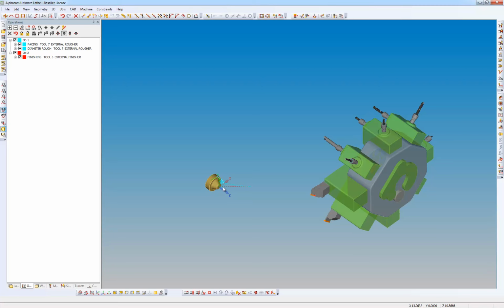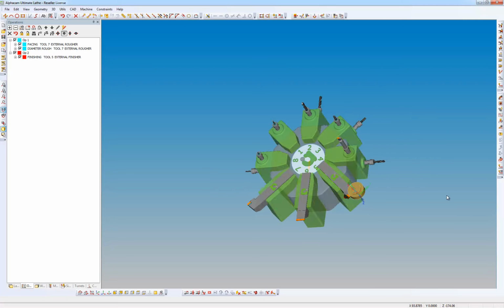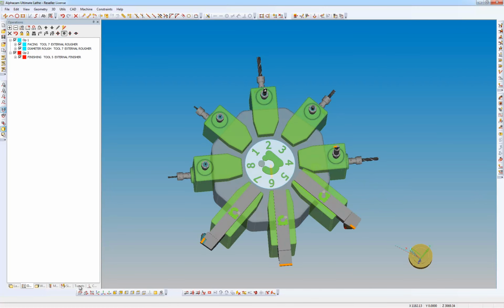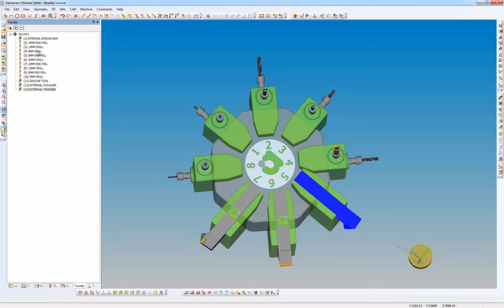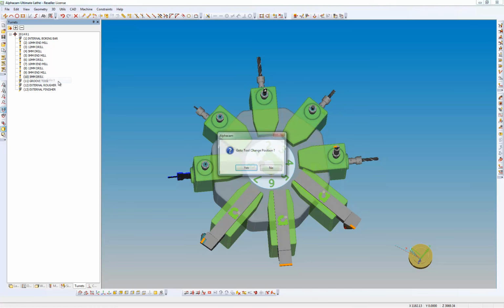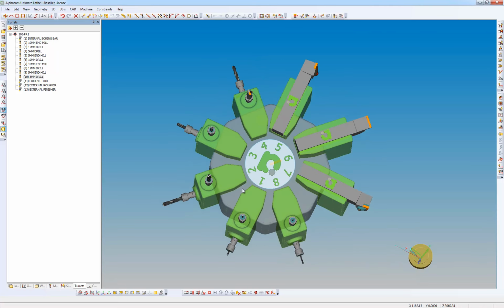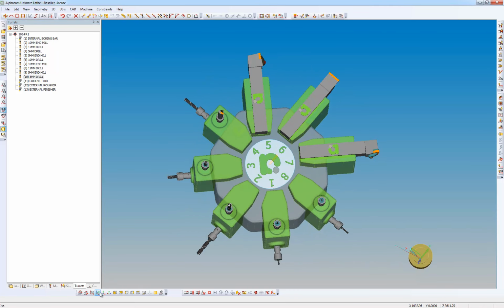What I now want to do is to select the tool to drill the holes. If I go to my turret, I can just look at the different locations, and it highlights the tools in the turret. So I've got periphery drills and axial drills here, so I need to select the one. So I highlight it, select the tool, go to tool change position for the last tool. How do I want to get there? Okay, let's go to the ISO view.